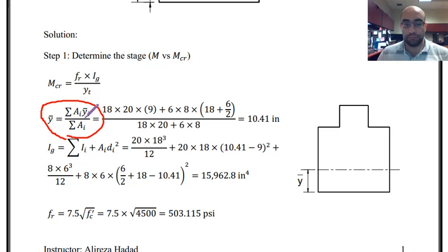We talked about it, I believe, even in high school physics, the basic equation. But from strength of material, we know this is how to find centroid of geometrical shapes. Summation of area of each shape that we have in the section multiplied by its own centroid from one origin point, and then dividing it by summation of areas.